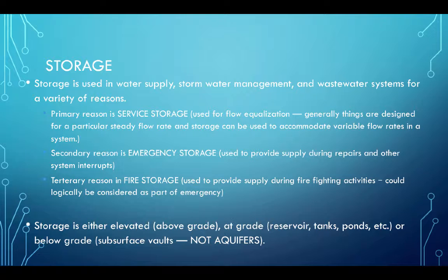First is service storage, which is used for flow equalization. Generally, we design things for a steady flow rate, and storage is used to accommodate variable flow rates in a system. That's how it's used in water supply. Flow equalization is also used in wastewater treatment.